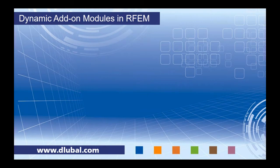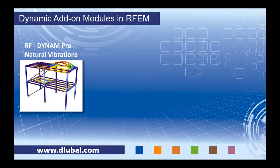So regarding the dynamic add-on modules in RFEM, RFEM is our main program. This is where we're going to fully model the structure. We can load it with various static loading and run an analysis. But anything to do with dynamics, whether that's natural vibration, forced vibrations, or seismic analysis, does require one of our dynamic add-on modules. So the first is RF-DYNAM Pro Natural Vibration.